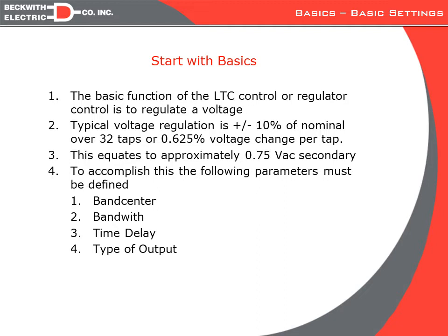windings, and typically with each winding we can vary the voltage a certain percentage. So all single phase regulators and the majority of LTCs will have 33 taps: 16 raise, 16 lower, and a neutral. At the neutral position, the voltage coming in is the same as the voltage going out. The incoming voltage is typically referred to as the source side voltage, and the outgoing would be referred to as the load side voltage.